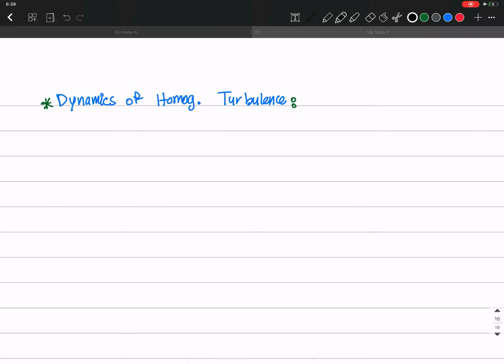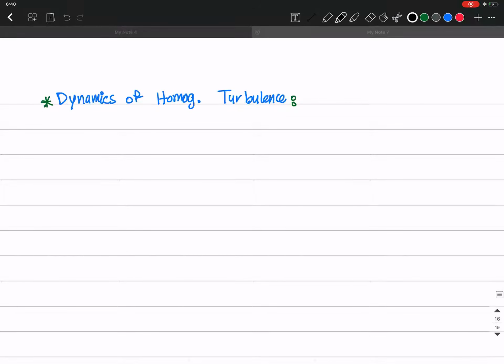Hello everyone. In this lecture, we are going to start a new topic and we are going to focus on characterizing the dynamics of homogeneous turbulence. So what I'm going to do is write an equation for instantaneous fluctuating velocity that we already had before, and then do some manipulations and derivations to get to an equation. And then after that, we are going to assume homogeneity in turbulence, and I'm going to discuss what that means to get another equation for homogeneous turbulence.